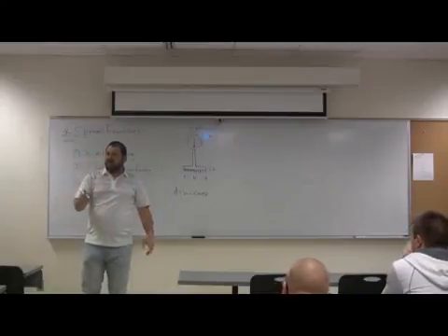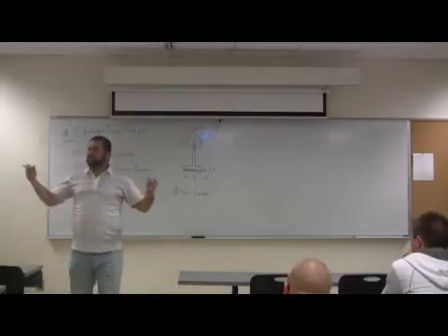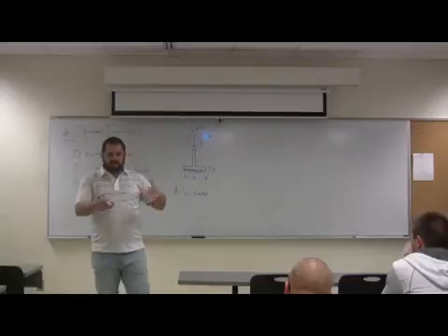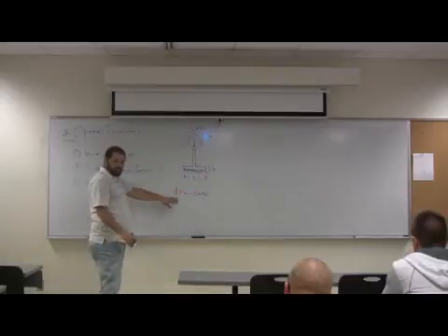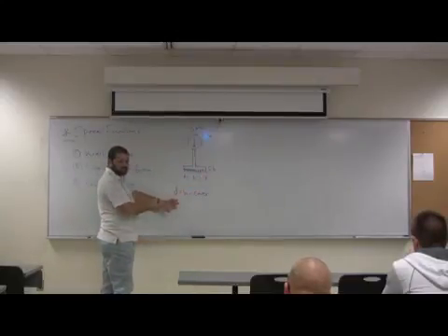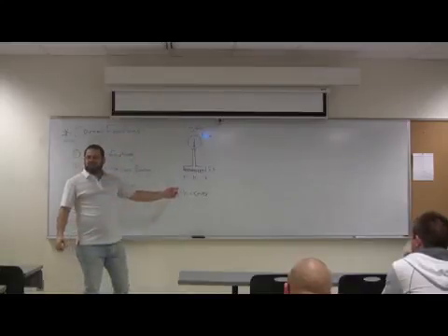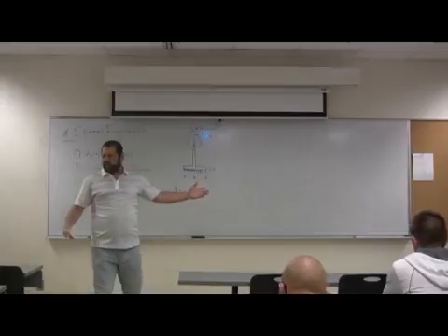Why is the cover high in foundation? Because there are sulfates and some other contaminants in the soil. These may come into the bars and cause corrosion. Okay? So usually clear cover according to the ACI code is 3 inch. So if you want to take d roughly, either H minus 4 or H minus 4.5.